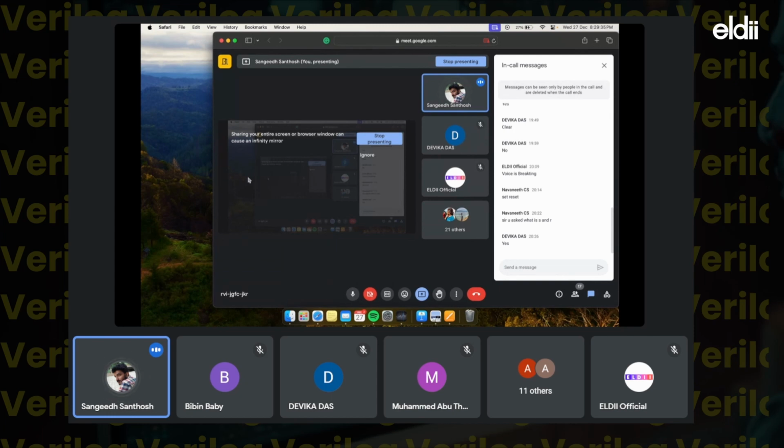If we are not representing every combination, there will be an indeterministic state. So the system will create an unwanted latch and store that signal there. According to our design requirement, we have to change the code accordingly. For that, we are using synthesis. Every gate level, behavioral and data flow are synthesizable, but switch level modeling is not synthesizable because we are using NMOS, PMOS for driving. That is the lowest basic element that cannot be further synthesized.